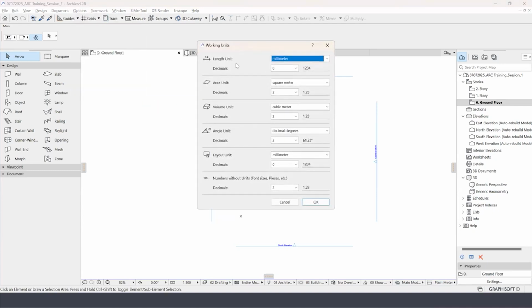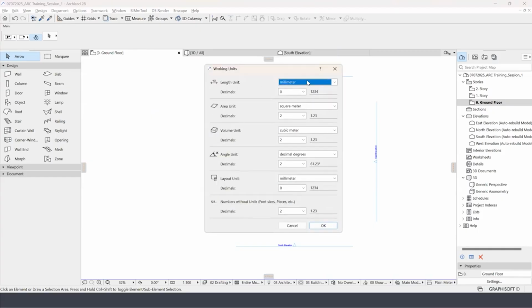So I'm going to click on that, and it will ask me which unit I'm working in. I'm going to work with millimeter itself, but if you want to work in a different unit, for example, feet and fractional inches, you take that and you give maximum precision. I always suggest when you start the project, use maximum precision, and later you can filter out the precision and work. The other way is always hard to do. So make sure you remember those points as well. And if you're using meter, make sure you give at least 3 or 4 decimal points, depending on how your office functions. Anyway, I'll just go for millimeter and give it probably 1 decimal. Not required, but you can have that much precision here.